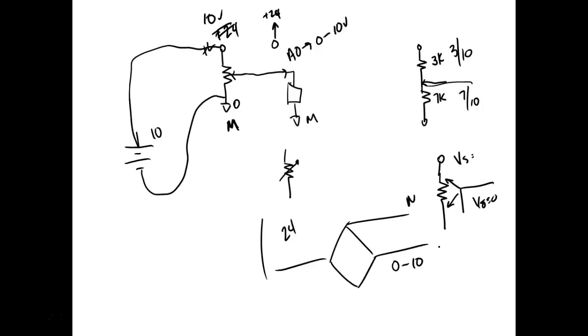The 314s do not have an internal power supply, so what does that mean? We have to have an external power supply. If you look at the Amatrol line, you'll see every one of them has a power supply. When y'all go back and put your Siemens PLC in the back, you're going to have to disconnect the power supply in the back, because ours is powered up through the power supply that's on the thing. Does that make sense? Everybody okay?